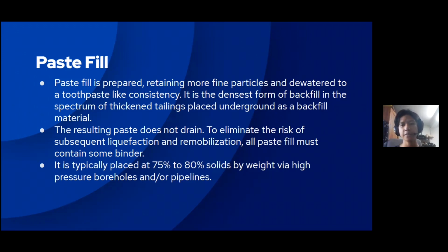To eliminate the risk of subsequent liquefaction and remobilization, all paste fill must contain some binder. Binder is cement, so paste fill must be mixed with cement. It is typically placed at 75% to 80% solids by weight via high pressure boreholes or pipelines.